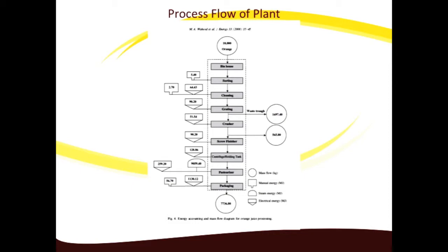In conclusion, the major exergy loss took place at the pasteurizer with an inefficiency of 90%. This was a result of the use of steam for the heating of the process stream. One method of improving the thermodynamic performance of the plant is by the use of process heat integration.